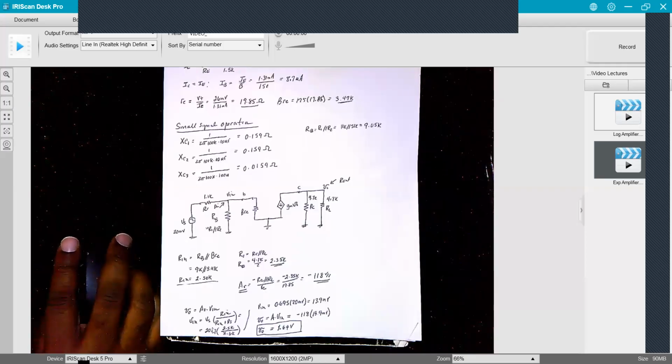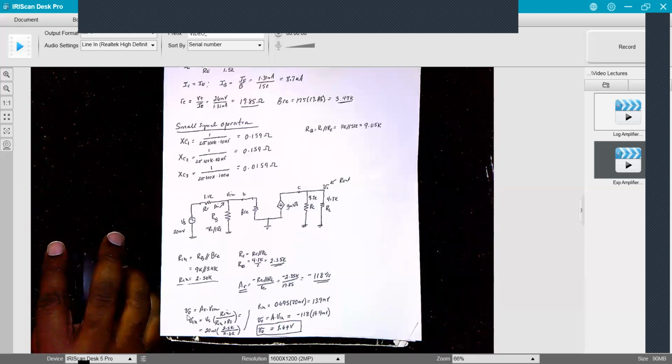And so then I got down here, starting to run out of space. But what we asked for was, what was the output voltage? We know what the gain is, but we have to find out what the actual input voltage is as a function of my source voltage here, which is 20 millivolts. That's why we calculate our input impedance, because if I have a voltage source, a series source resistance, into this resistance node here, I basically have voltage division.